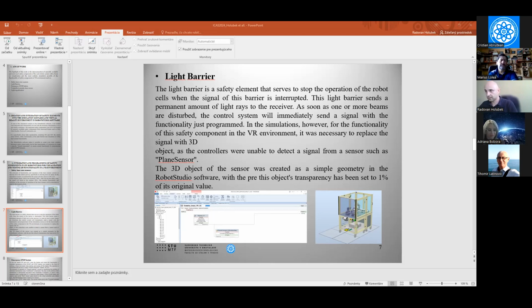You can see in the left picture this is a joint sensor, and the data of the position of the mechanism is subsequently provided to the comparer, in which, if the measured value is greater than 0, the signal is sent further. For the start button, the signal is sent via the start digital output directly to the virtual controller using station logic. The stop button sends the signal to two sources.